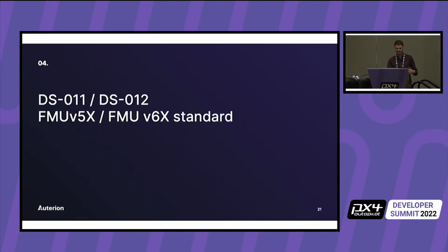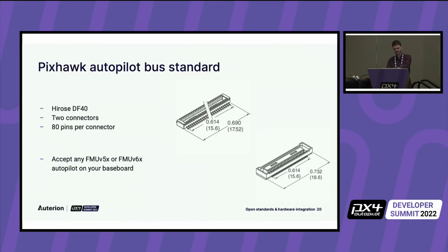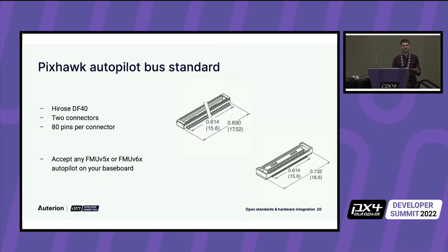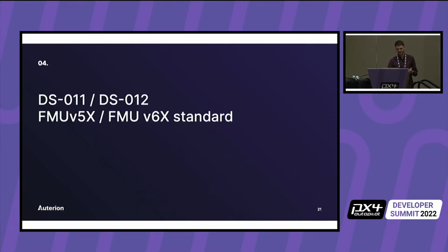With that, we go straight into the actual standards for the autopilots. We've talked about the connector. Now, for the autopilots themselves, there are also standards. The connector standard is really about mechanical and electrical compatibility, but the Pixhawk Autopilot standard is about software compatibility. You can have the pinout and connectors well defined, but it doesn't mean the software will run on it, because the software runs on the actual components, the actual drivers, on the actual sensors that you have on the autopilot.